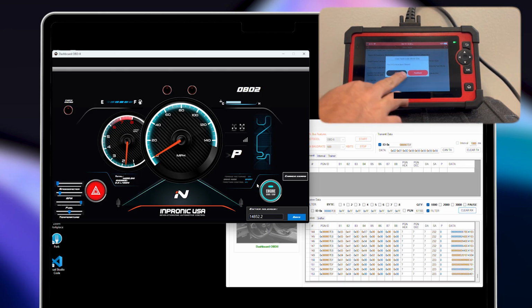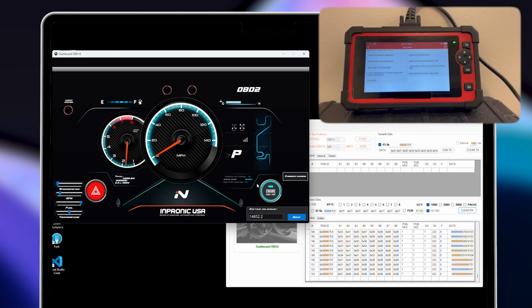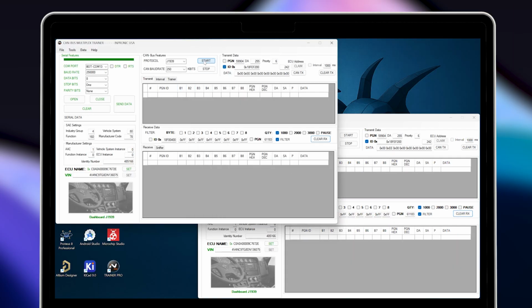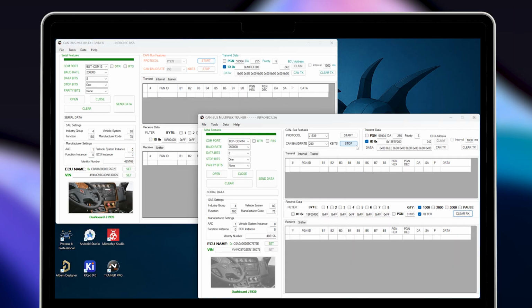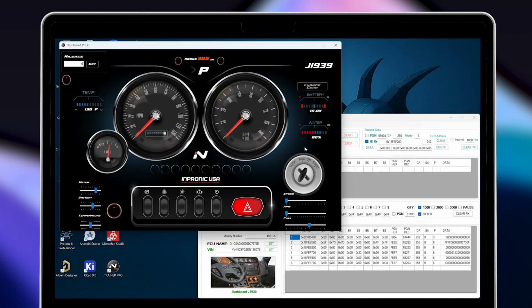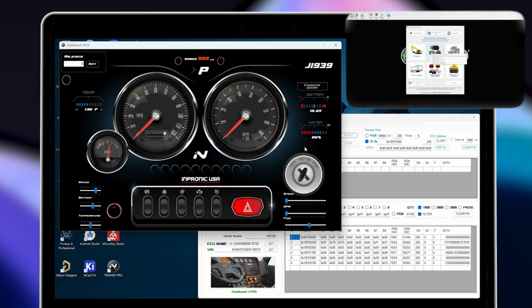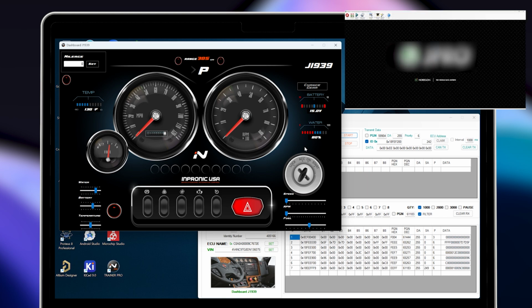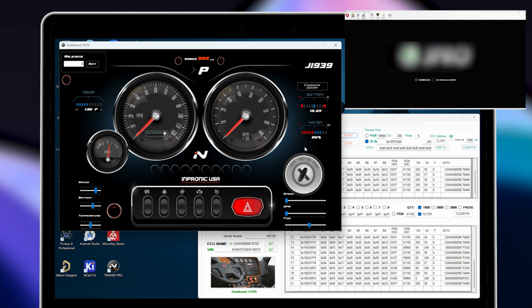Now we're going to learn how the J1939 dashboard works with external software. We switch our protocol to J1939 dashboard and open the ports in both windows as well. In one of the windows, we open the dashboard. When we start it, it already provides some information without sending any requests. We open our heavy-duty diesel software, select the J1939 dashboard connection, and the data immediately begins to flow.